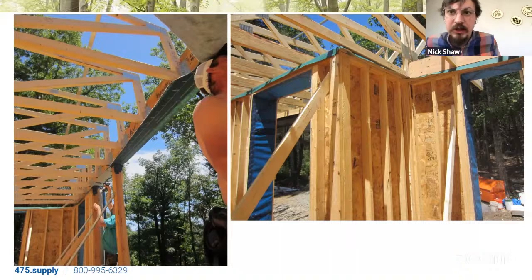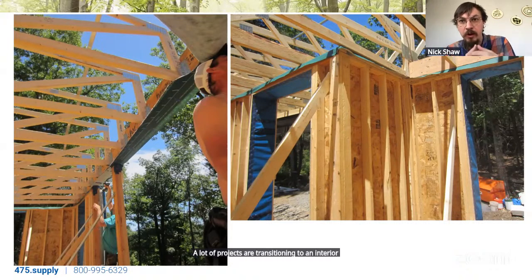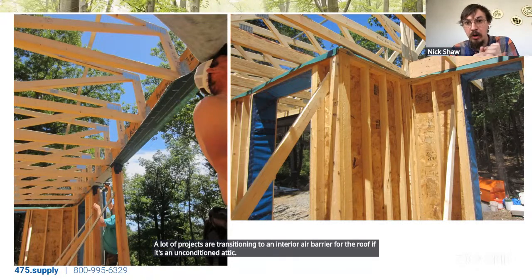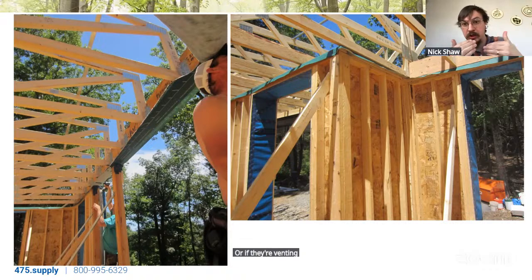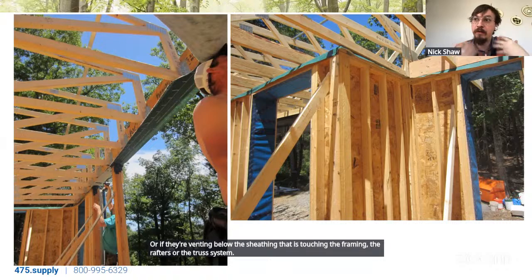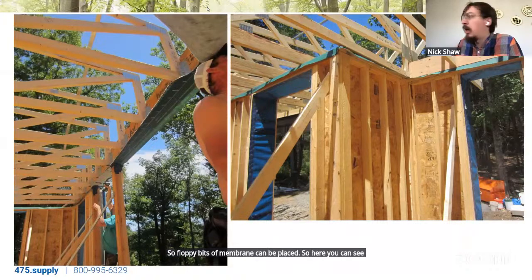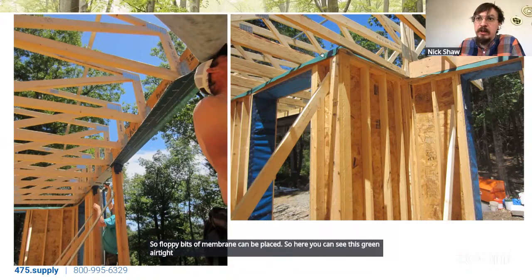A lot of projects are transitioning to an interior air barrier for the roof, if it's an unconditioned attic, or if they're venting below the sheathing that is touching the framing, the rafters or the truss system. So floppy bits of membrane can be placed. Here you can see this green airtight membrane, and that it's lapping to the exterior and coming inwards.